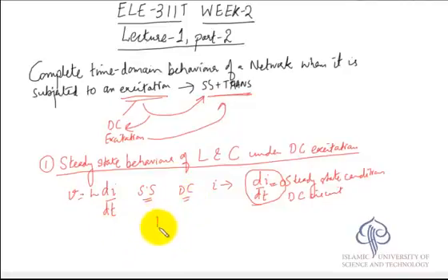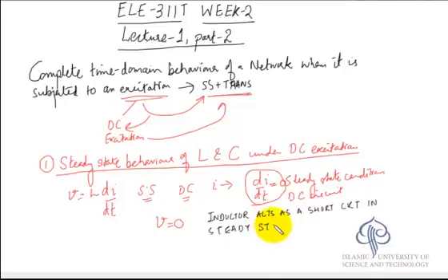So this actually means that the voltage across the inductor will be zero, and that's why we say that the inductor acts as a short circuit in steady state, and this is with respect to DC circuits, not with respect to circuits which have other sources of excitation.